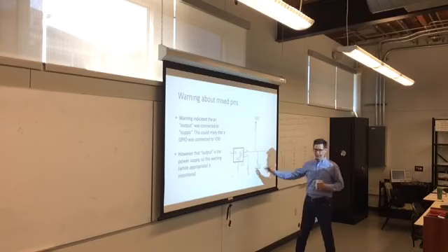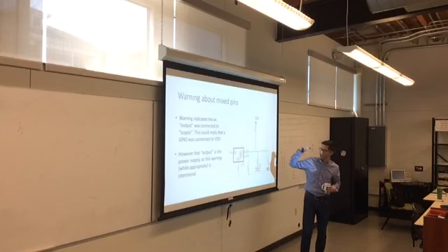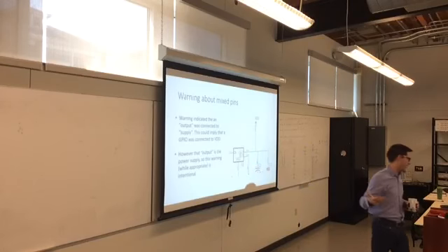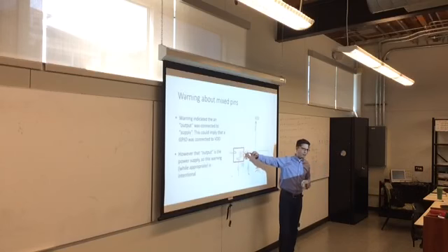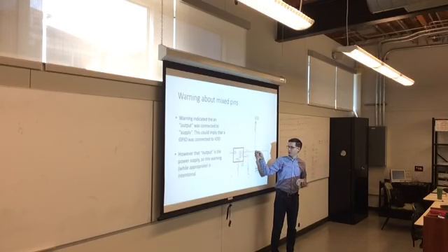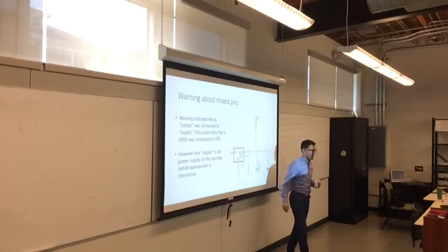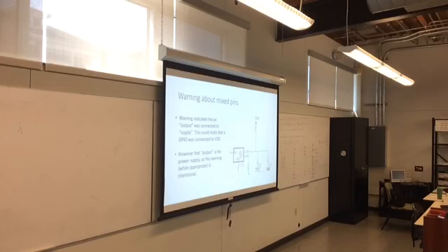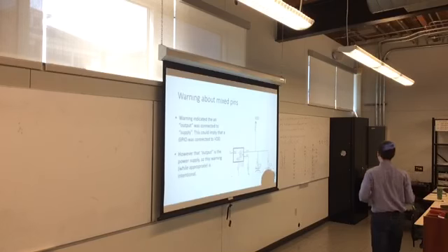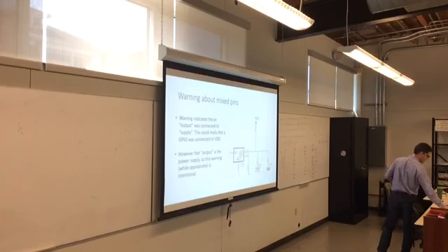At the same time, as I said, you might get warnings on the electrical rule check about pins of different types being connected. The error here is that an output net and a supply net are being connected, and it says, well, that's not good, they're of different types. However, you know what you're doing here by attaching the output of the power regulator to the supply pin, which is VDD or VCC. So you will get the warnings. The warnings are helpful, but sometimes you need to read them and interpret them to make sure they're what you want. Questions so far?